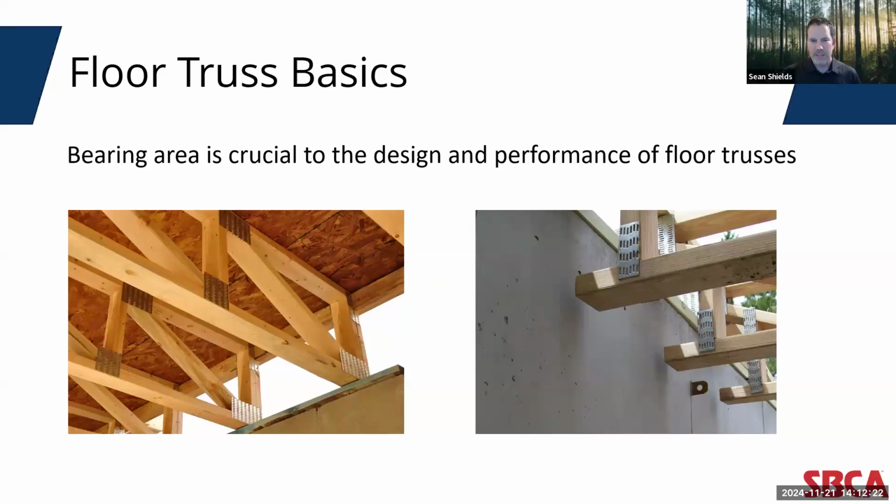One other really important concept of floor trusses is bearing area. Bearing area is crucial for floor trusses because it determines how effectively the truss can, 1, transfer its load to the supporting wall or beam, 2, prevent crushing of the bearing surface, and 3, ensure the structural integrity of the entire floor system. Now, if the bearing area is too small, the concentrated load coming through the truss at the bearing location can exceed the capacity of the wall, leading to potential structural failure.